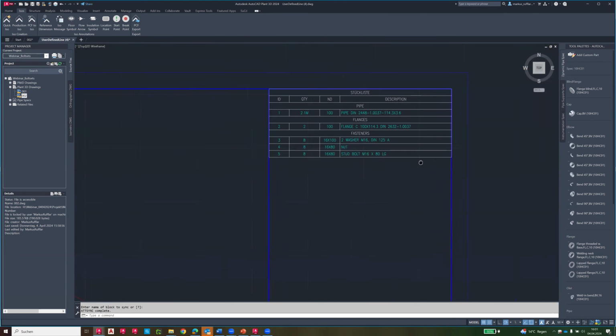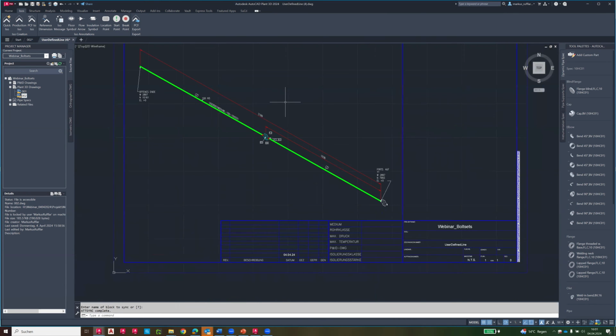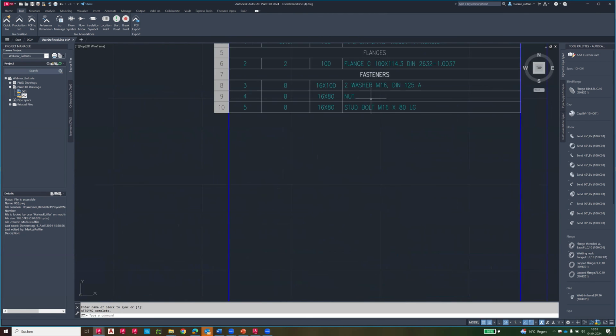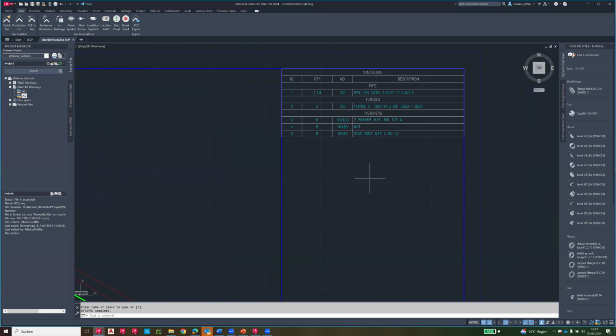Let's summarize everything. To reach our goal of creating individual bolt sets in Plant3D, it's important that we first modify our default connectors config and add two additional bolt sets there. We also create two additional bolt sets in our catalog or spec.